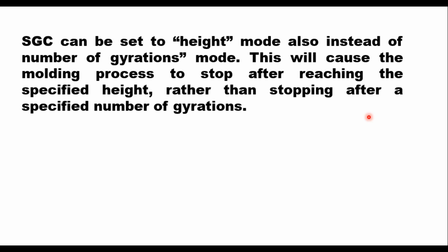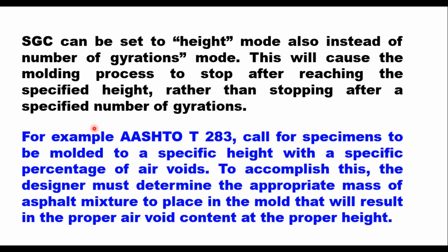The Superpave gyratory compactor can be set to height mode also, instead of number of gyrations mode. And this will cause the molding process to stop after reaching the specified height rather than stopping after a specified number of gyrations. For example, AASHTO T283, that is the test for TSR, tensile strength ratio, requires that specimens be prepared at 7% air voids. To accomplish this, the designer must determine the appropriate mass of the asphalt mixture to place in the mold that will result in the proper air void content at the proper height.